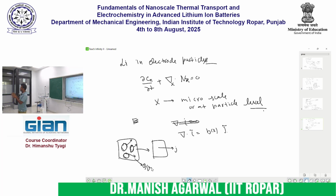In actuality the heat is generated only at the interface, but I don't want to resolve the interface, so I assume the heat is generated uniformly. This way I convert the boundary quantity, which is per area, into a volumetric quantity by considering it as a source term. Now the domain is homogeneous.